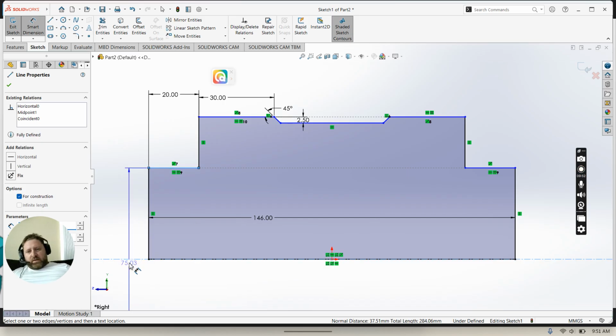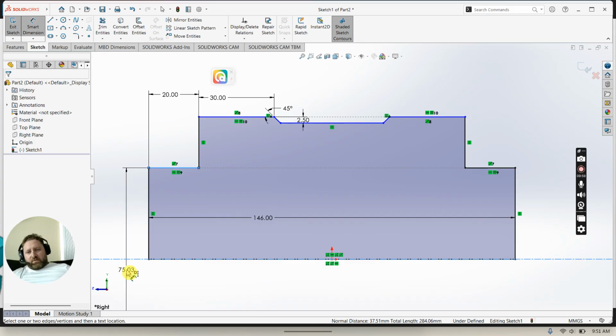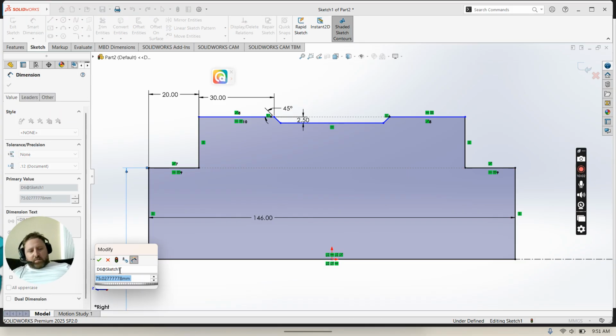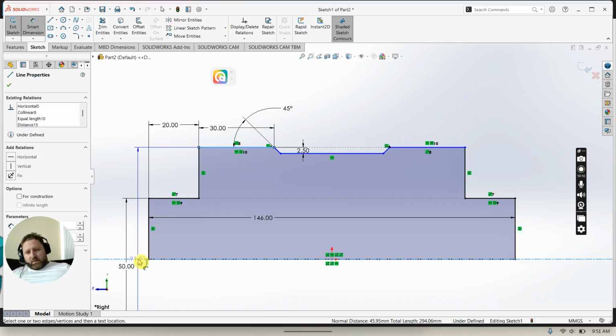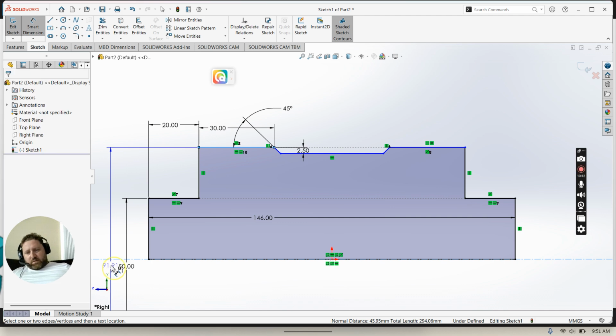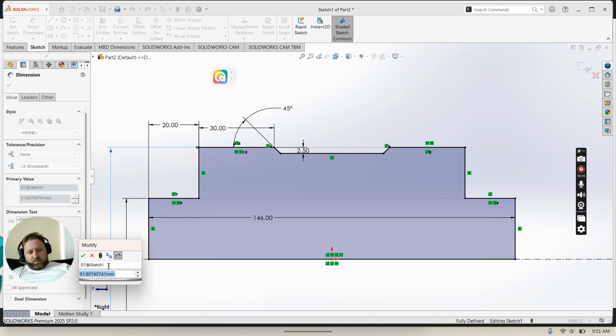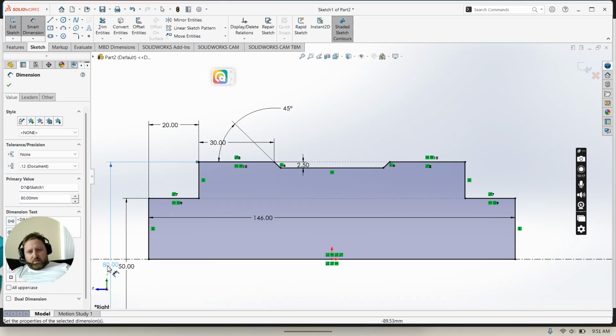And instead of it giving you a radius, if you went to the solid line or hold above, if you come below, you can have this give you a diameter. And like we said, we're going to be at 50. And then this up here of the center line will be 80. And there we go. We're ready to revolve now, which is the key of this whole, I guess I'll call it the heart of this operation.